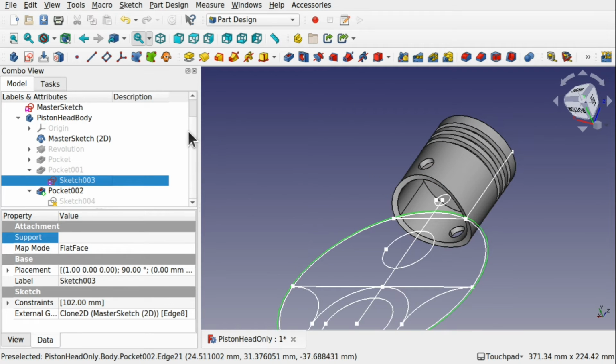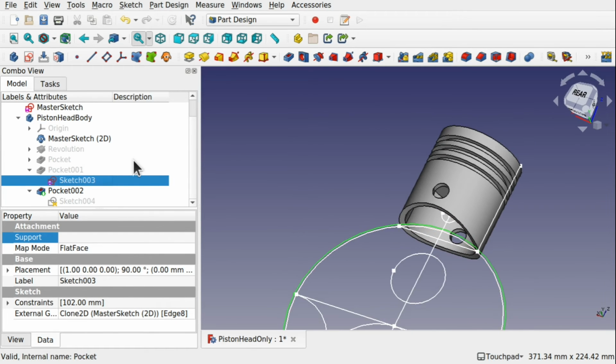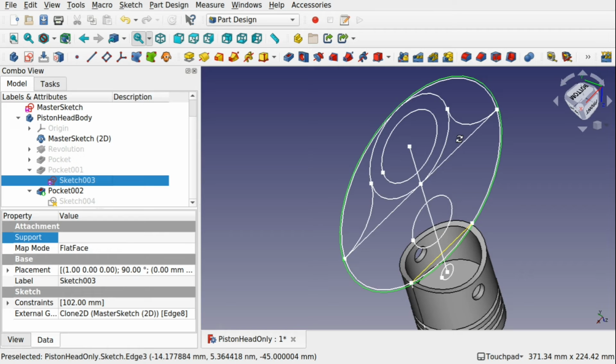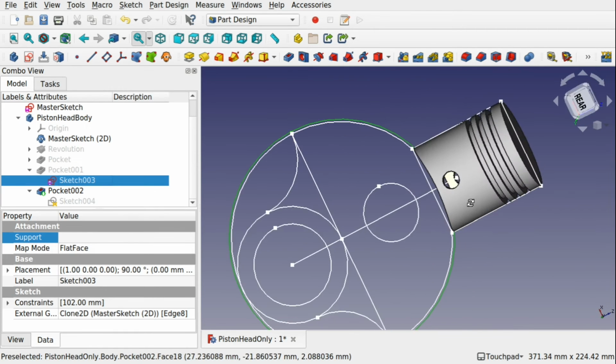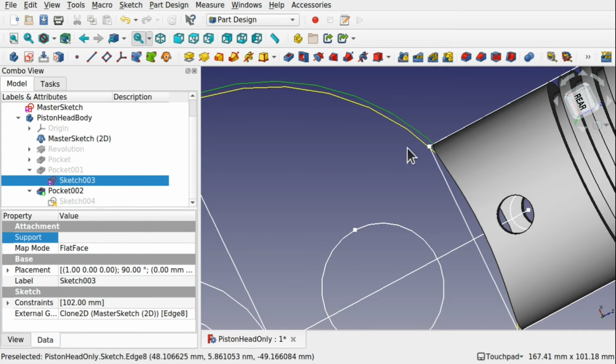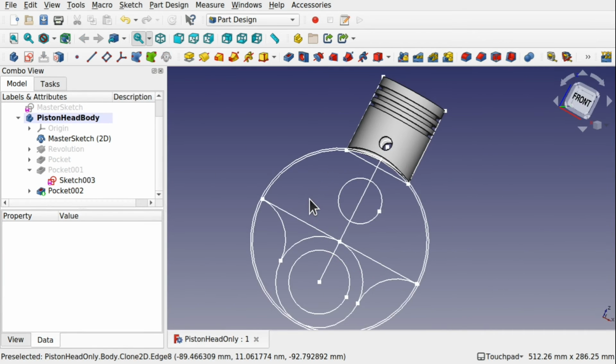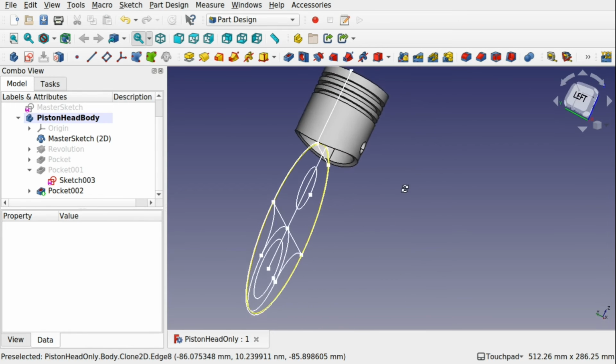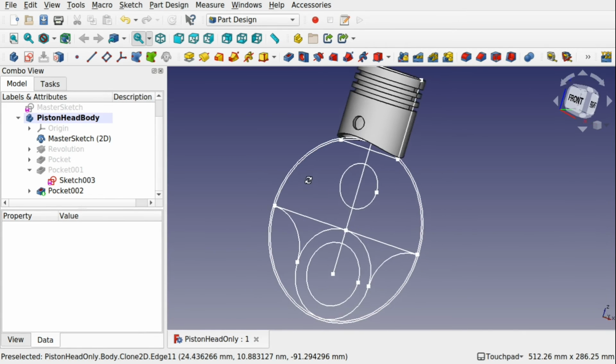So we've refined this model. We've got rid of the datum constraints that control this edge here. We've got rid of the datum planes, which made the model more complex. And we've learned how to reference constraints inside the master sketch by giving them the name. One thing to mention is that these amendments you won't see in the other videos, video 2, 3 and 4, because we've completed those videos and this is just a refinement we're going back over. There's no point in going back and overwriting those videos and adding those amendments in, because you can use them as reference back to see what I've actually done.